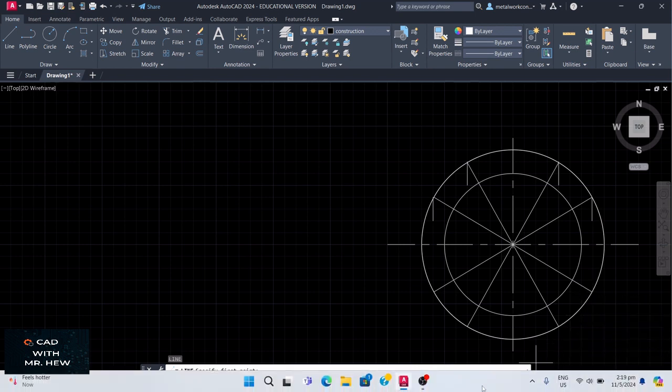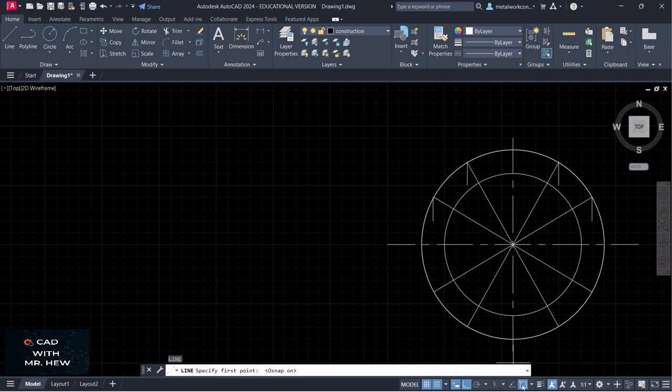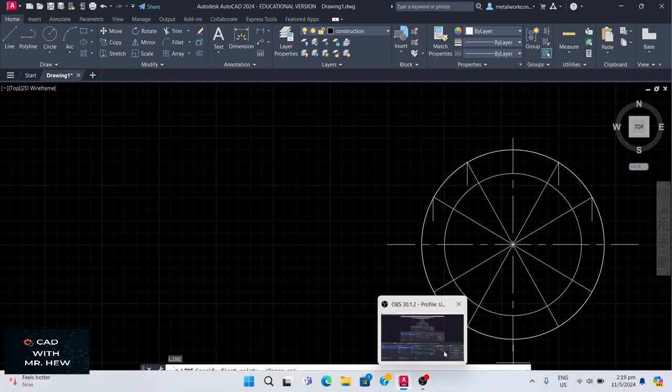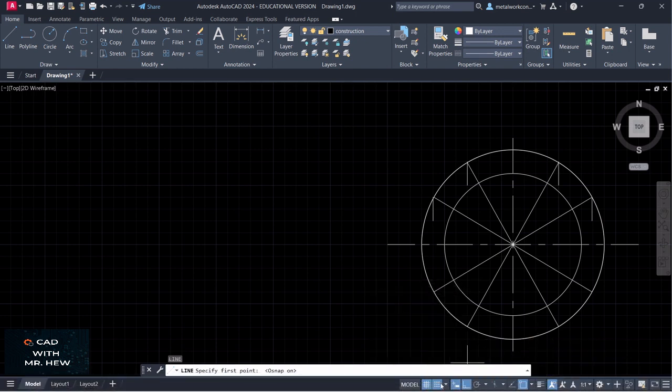We need to turn on the object snap here now. And we need to turn off the snap. So we can pick up this point, right? This point doesn't coincide with the grid. So we're going to go up there, enter. Enter to get the last command, from there going up. We need to turn off object snap right now and then turn it on. Enter. We can turn it on now to pick up the other point, which is here.